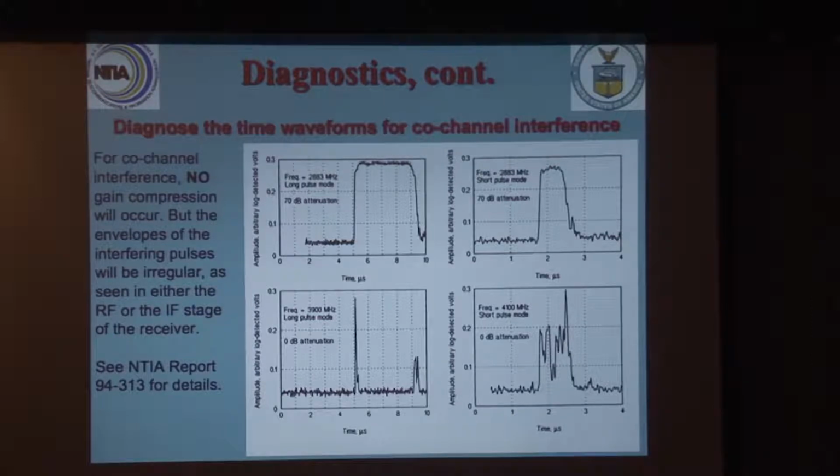But, this is important, if we're seeing energy in a pulsed emission spectrum not on the frequency of the transmitter that's producing the pulses, but off-tuned from that transmitter frequency by 200, 300, 400 megahertz, the receiver is only seeing a small subset of the total set of lines in that emission spectrum. If you observe a small set of lines in the Fourier spectrum, you do not, in the time domain, form a nice, clean pulse envelope. Instead, you form a pair of pulses at the leading and trailing edges of the pulse. And these are vernacularly called rabbit ears by technicians.